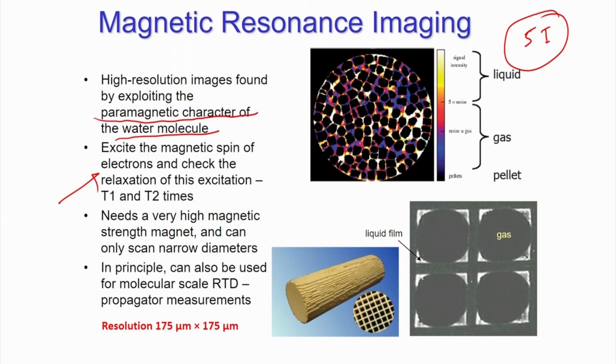Okay. So, this is a typical photograph of MRI of a packed bed, okay, 3-phase flow actually, where the gas, liquid, solid is there, and you can see that the dark black color spots are showing the solid phase. The yellow color is showing the liquid, and the red color is showing the gas. So, you can see that the gas is making a film around the particle, and then around that the liquid is flowing inside. So, this is a typical figure of the trickle bed.